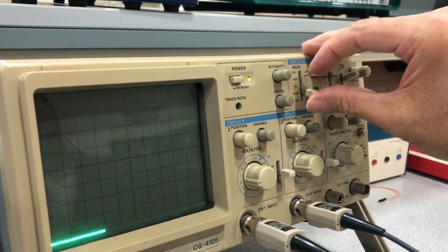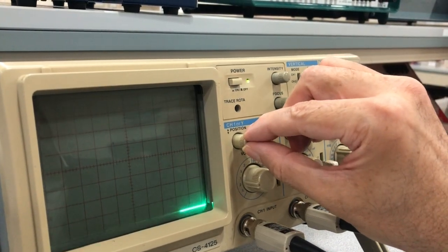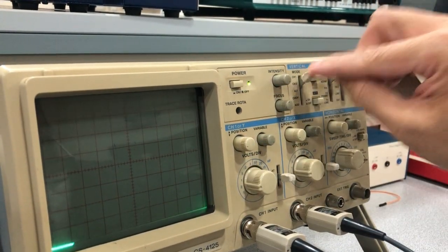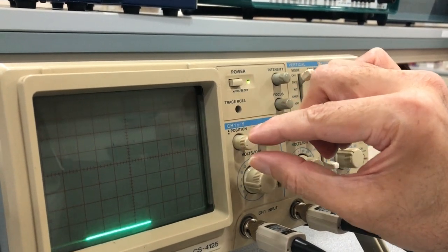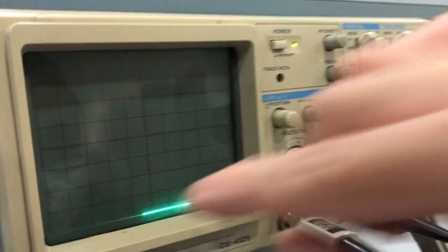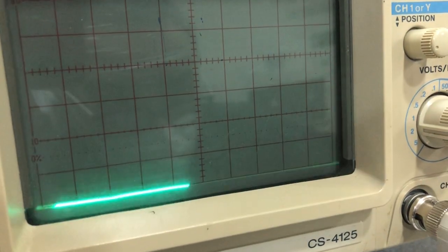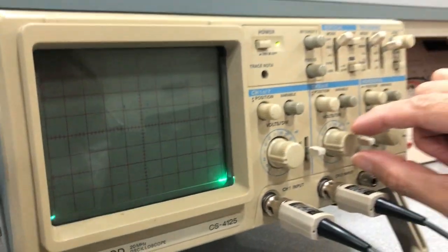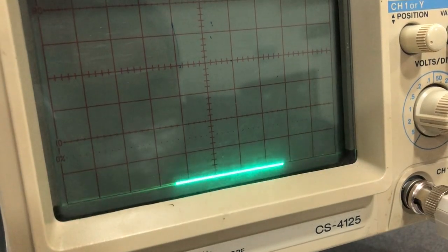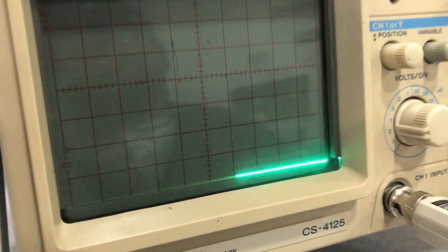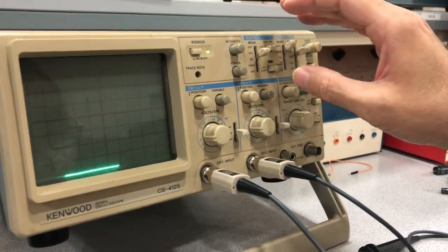Vertical position, one channel at a time is better. This is one channel. I went to channel 1, plotting alone in vertical mode. I see the black horizontal line is in the center of my thick green illuminated scan, and then I go to channel 2 and adjust its position. This is how you need to make precision measurements in the old style analog scope.